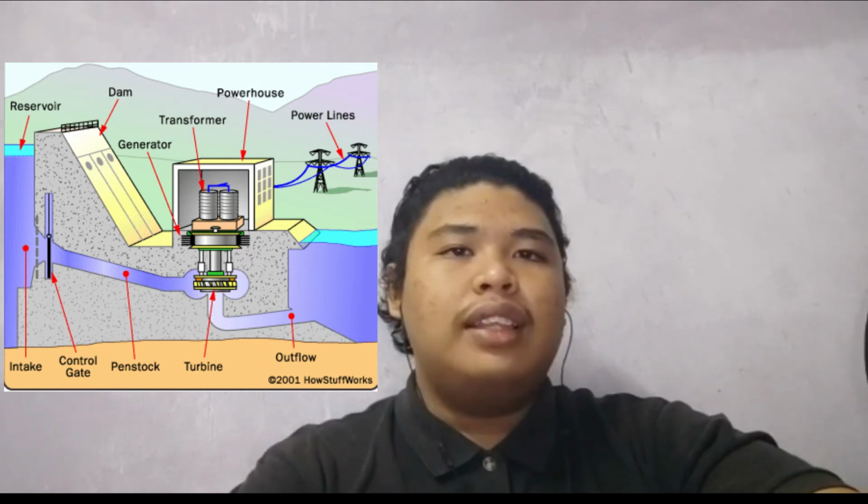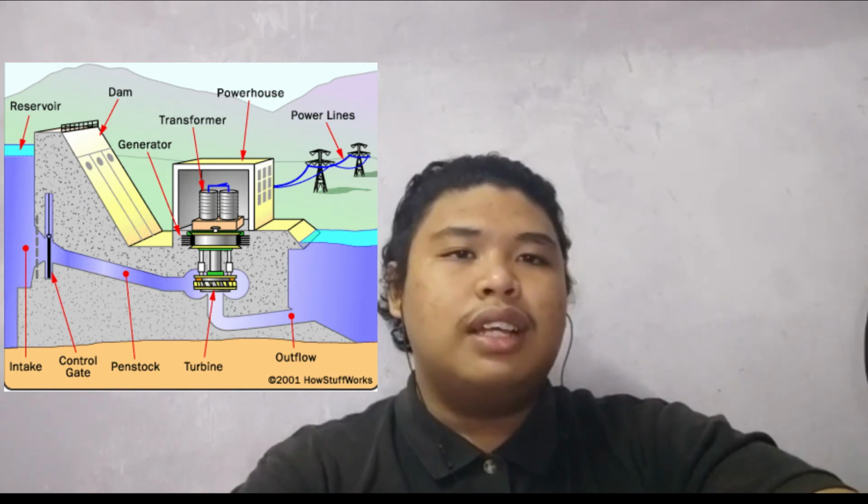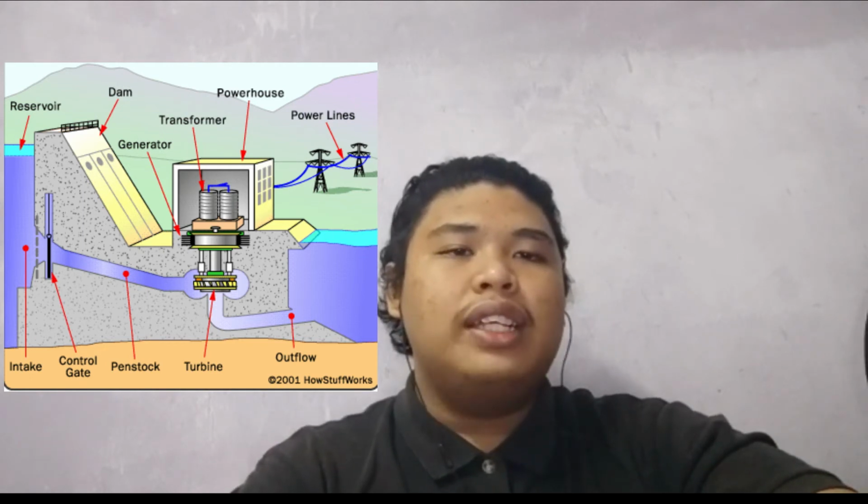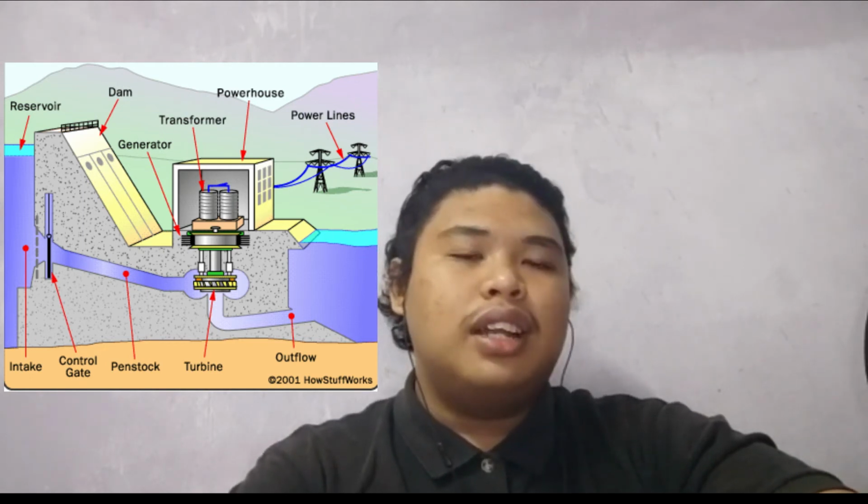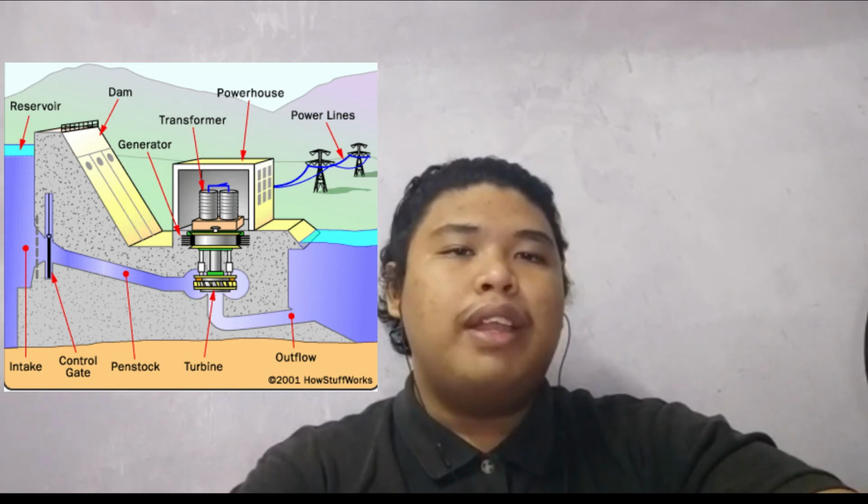The amount of electricity that is generated is determined by several factors. Two of those factors are the volume of water flow and the amount of hydraulic head. The head refers to the distance between the water surface and the turbine. As the head and flow increase, so does the electricity generated. The head is usually depend upon the amount of water in the reservoir.